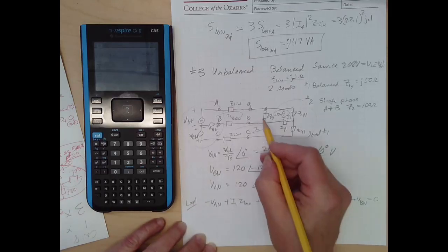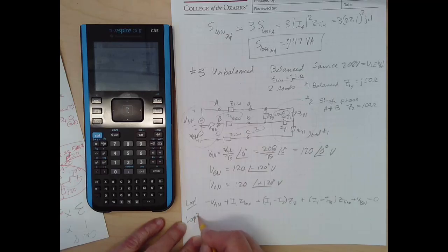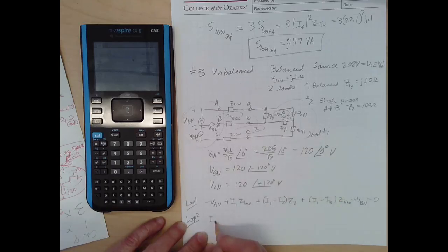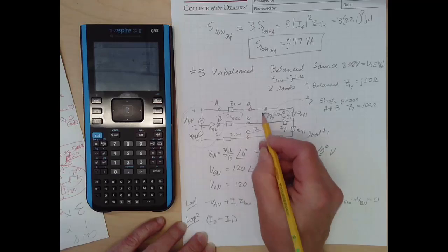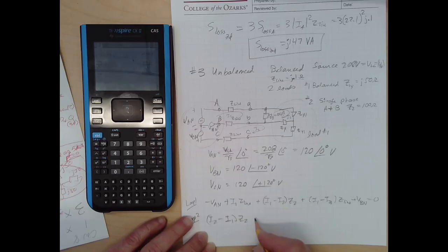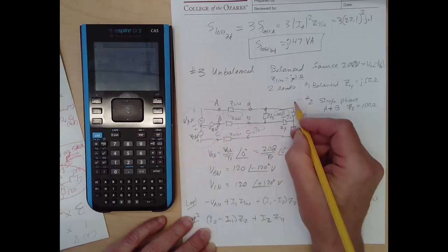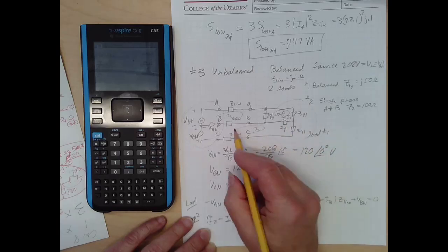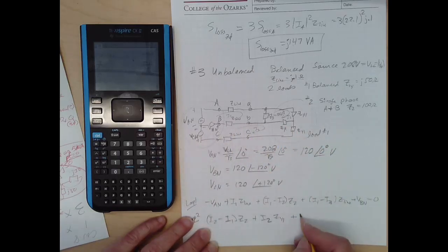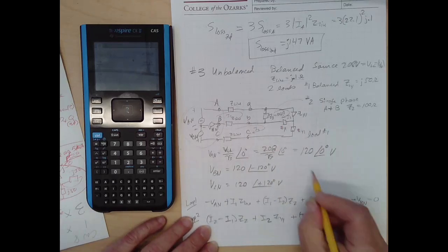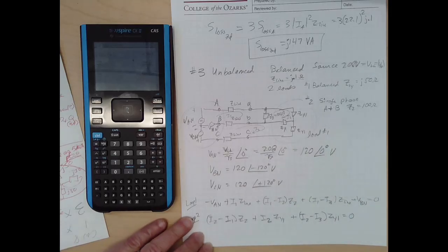And then we do a similar thing for loop 2. Let's start down at this spot here. So we're going to do I2 minus I1 times Z2 is the voltage plus to minus here, and then coming around this one, the only current out here is I2, so I2 times ZY1. Then back in here, we're going to have plus I2 minus I3. I3 is the current around this whole big loop, so I2 minus I3 times ZY1. And then we've gotten back to where we started, equals 0.